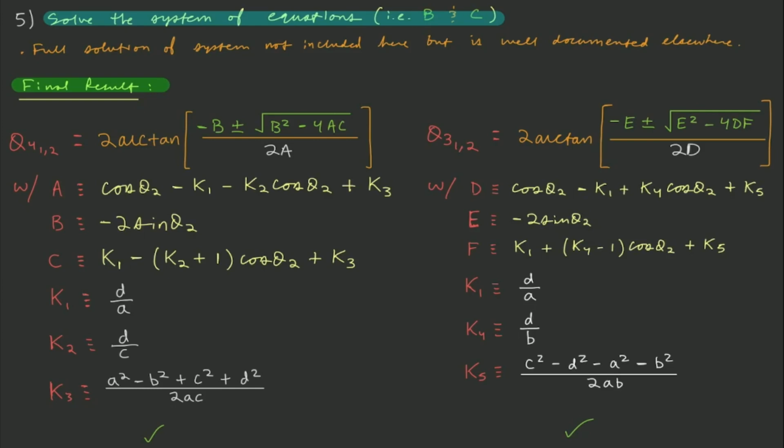Okay, so in this video, we're going to be reviewing an example problem of how to analyze the position of a 4-bar linkage using the position equations for a 4-bar linkage, which we derived in the last video and are now shown on the screen. If you'll remember, theta 4 is the angle associated with the output link, and theta 3 is the angle associated with the coupler link.